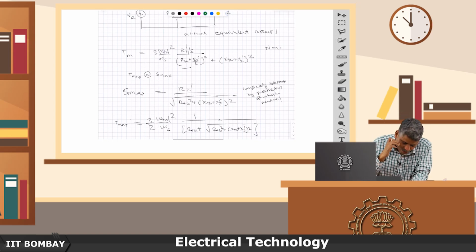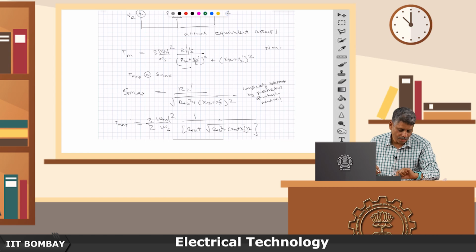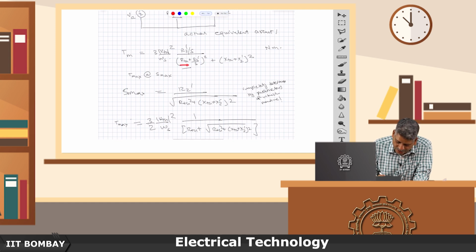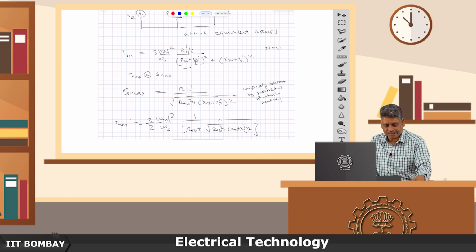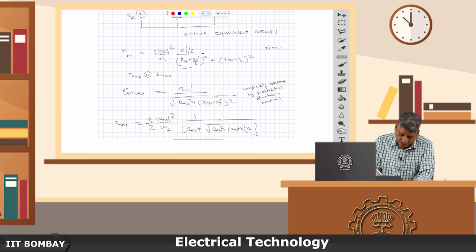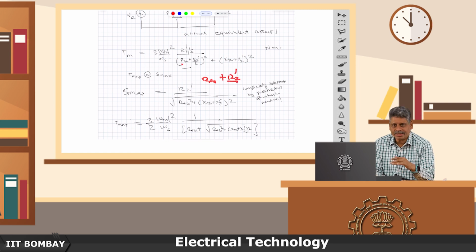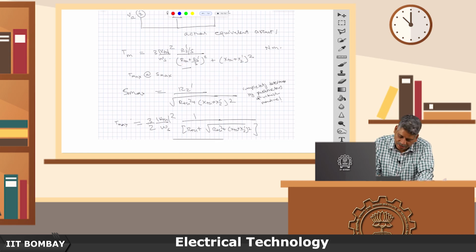At S equal to 1, basically R Thevenin plus R 2 dash comes into the picture. Now, this comes on the square of this term, R Thevenin plus R 2 dash, and this R 2 dash is altering due to the external resistance that we are adding.